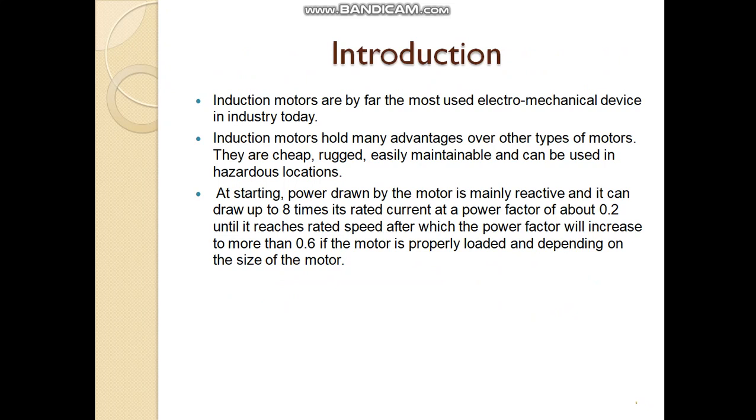It draws reactive power from the source to be able to operate, and therefore the power factor of the motor is inherently poor, especially under starting conditions and under light load conditions. To improve the power factor, reactive power compensation is needed. Where reactive power is injected, several techniques have been suggested, including synchronous compensation, which is complex and expensive, and switched capacitor banks, which require expensive switchgear and may cause voltage regeneration, overvoltage, and high inrush currents.